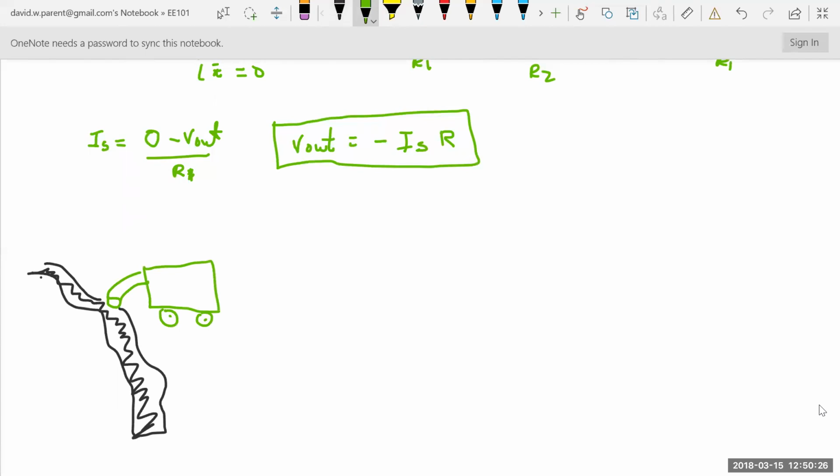And when less light is bounced back because this is dark, the voltage goes down. When it leaves the line, more light comes in, and so the voltage gets, well, actually more negative in this particular example. So even though this robot might use a microcontroller to control it, how do you get the signal into that microcontroller? And you say, oh, well, microcontrollers have A to Ds. Sure. But how do we convert light into a voltage that the A to D can use? That particular circuit. Okay?